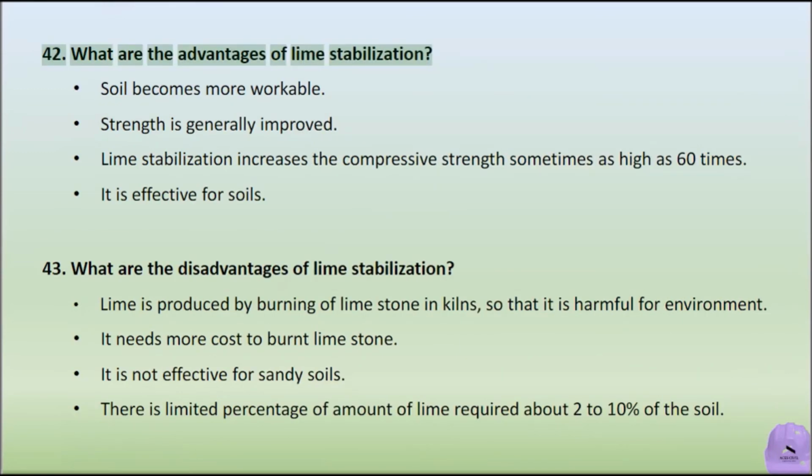What are the advantages of lime stabilization? Soil becomes more workable. Strength is generally improved. Lime stabilization increases the compressive strength, sometimes as high as 60 times. It is effective for clay soils.